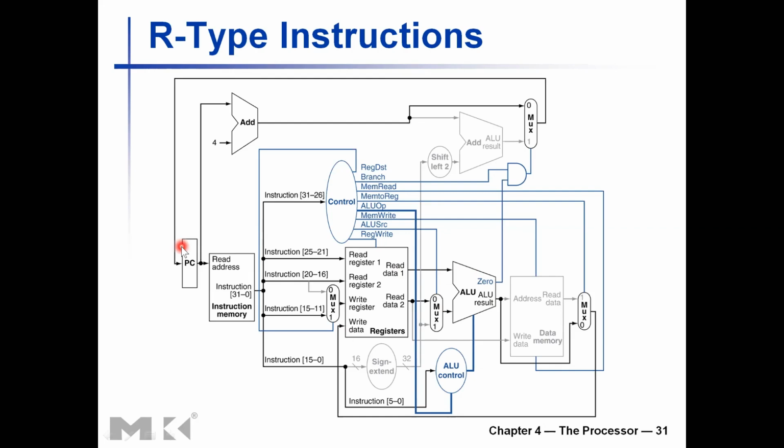The program counter is automatically incremented by 4 with the instruction fetching mechanism. So why are you incrementing it by 4? Each instruction word contains 4 bytes. So the byte address presented inside the program counter needs to be incremented by 4 to get to the next word.